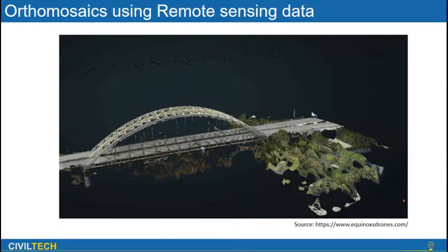What they do in that particularly is take a drone, fly it around the object, capture images at multiple angles, and then develop a three-dimensional model. They do a similar exercise at finer time intervals, so that if I take it today and then tomorrow, I can compare tomorrow's image with today's, right? And then I can find out if there is any crack or something like that. So these types of exercises are being done in many areas.